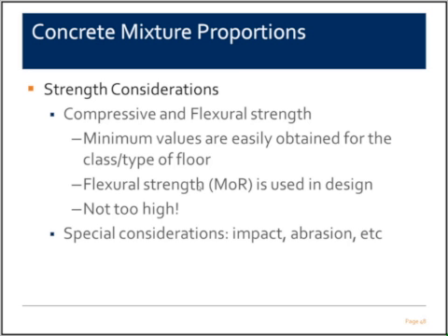We typically don't have too many issues of not meeting those minimum values. It should be noted that most of the design theories require a flexural strength or a modulus of rupture, so it's important to know what that value is going to be.